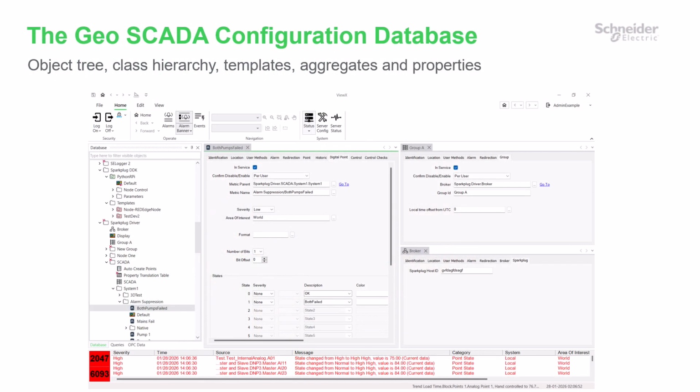I'm Steve, and in this video I'm going to demonstrate how to do configuration with Geo SCADA and Excel. Geo SCADA's database uses tables which we call classes, and they have rows which are objects, and those objects or rows have columns or properties like any other, so that you can add rows to create new objects and modify column data to change item properties.